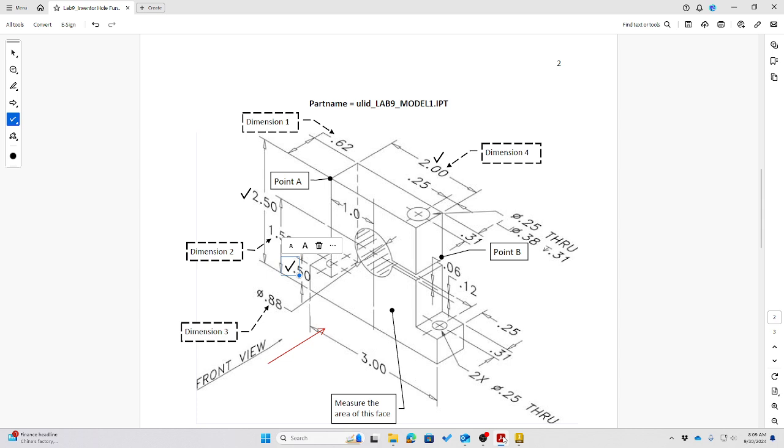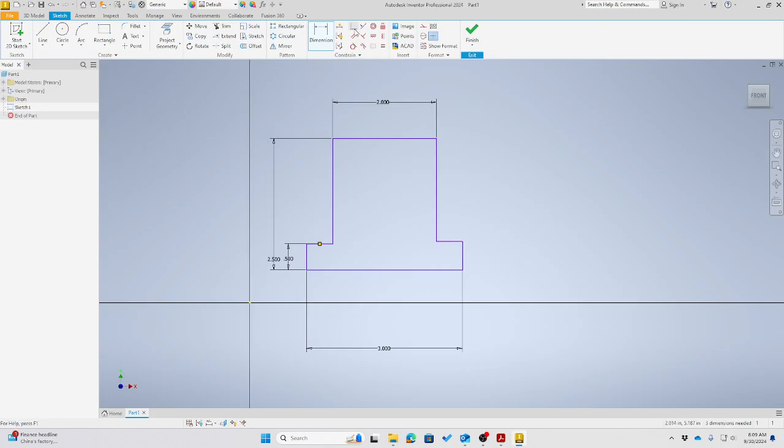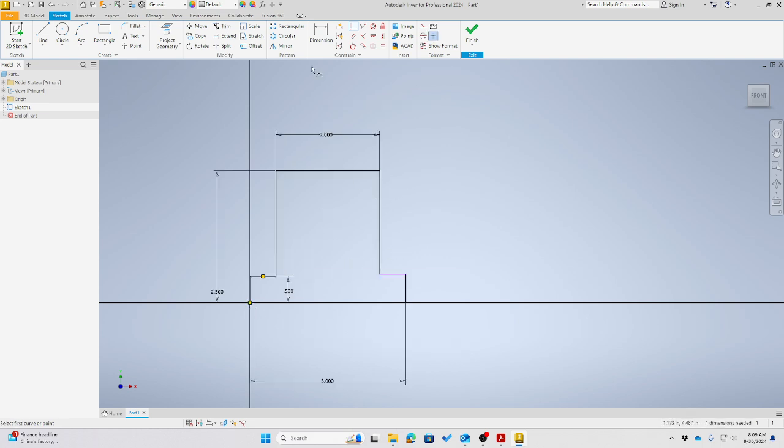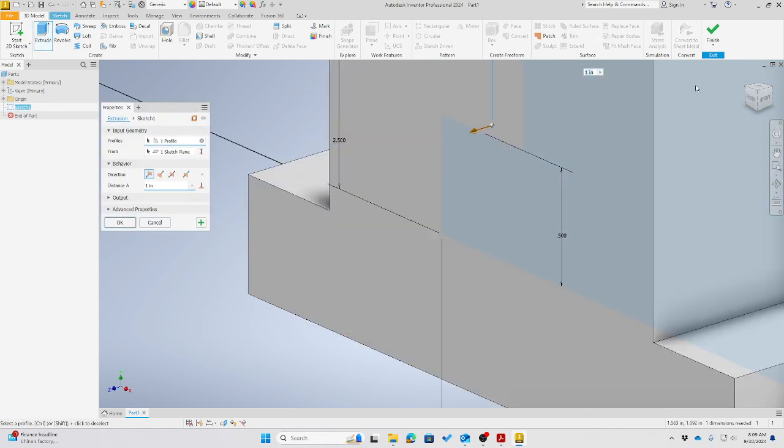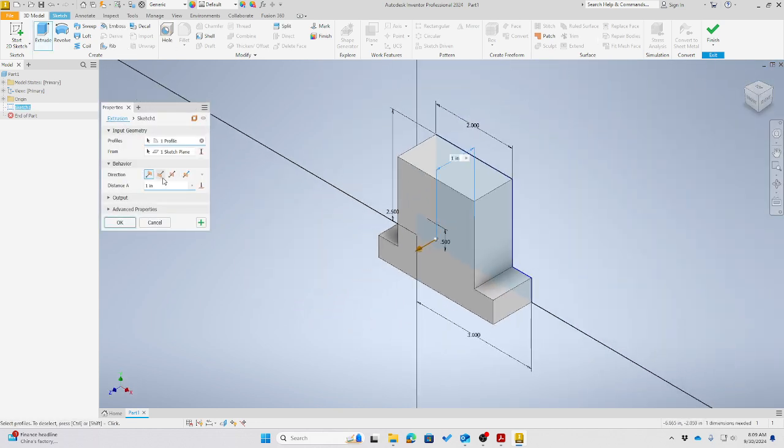Now we can use coincident to move this sketch to the pivot point. I can use this corner or I can use the middle of the line. It doesn't matter on this sketch, but in the future I prefer to use the middle line of this, but right now I'm going to use this edge. So click on this edge, click on this edge. Now we have a fully defined sketch. Now in the 3D model, from here I prefer to create an extrude using